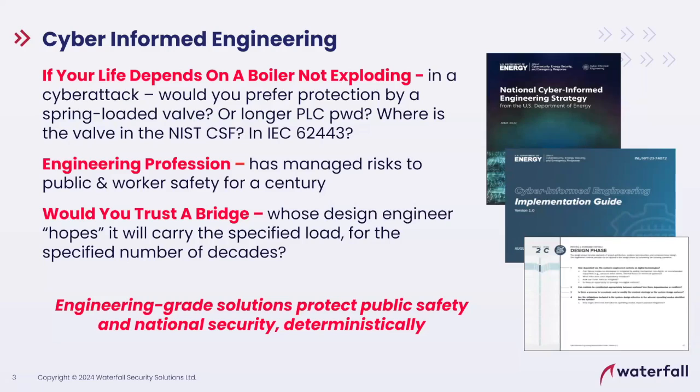Every one of us on the call, how would we like to be protected from a cyber attack that overheats the furnace under one of our boilers? Would we prefer a mechanical valve, an overpressure relief valve, that if the steam pressure in the boiler is too high, it forces a piece of steel against a spring, the steam escapes, and there's no explosion? Or would we prefer a longer password on the PLC controlling the boiler? Most of us would prefer the mechanical valve, thank you, because it will always do its job.